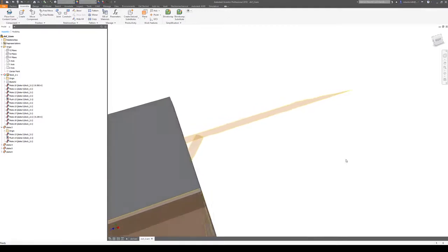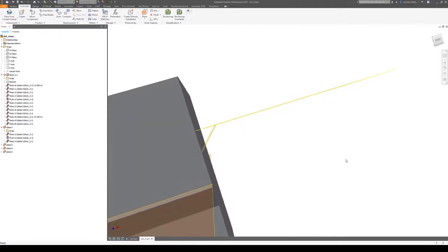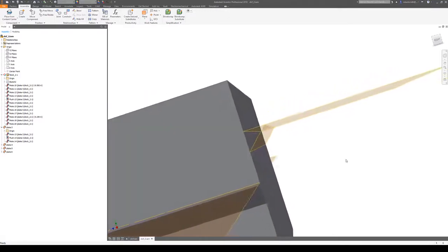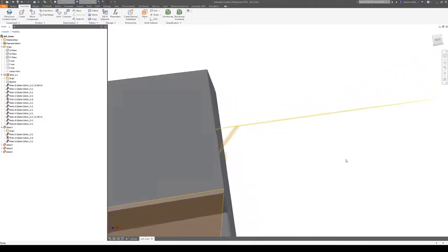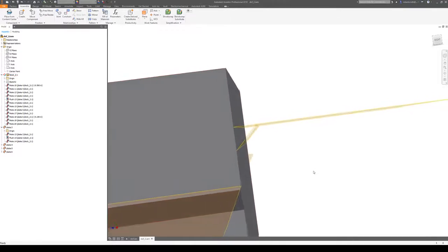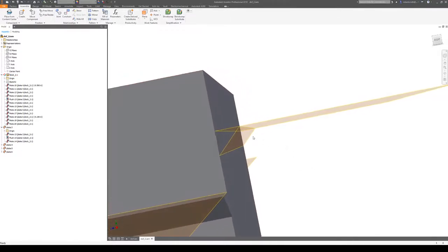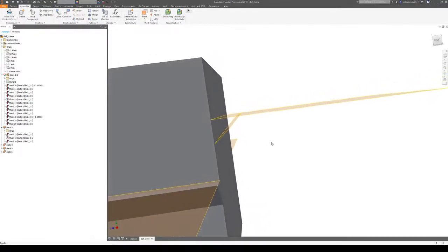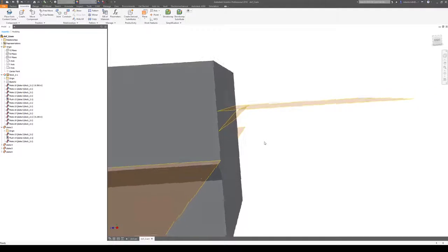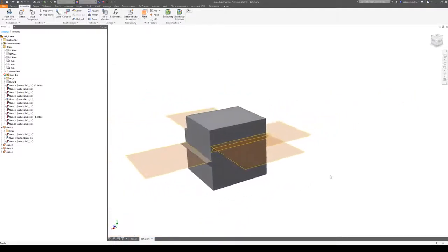I've seen stuff like this where, in this case, I've modeled two plate structures. Both of them would be shell elements, and the bottom one is kind of like a row of gusset plates or something like that. I've seen the same thing done, but with line-based bar or beam elements that just serve as structural supports to prevent that hinge behavior where the two meet.